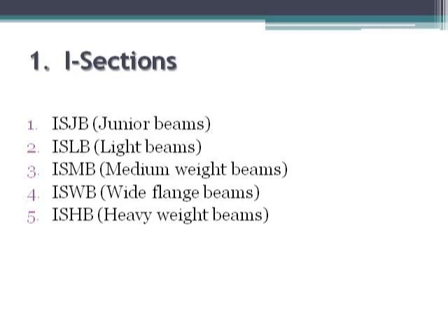Loads which are coincident with the major principal axis are called lateral loads. So for supporting lateral loads, we require more moment of inertia or section modulus about the YY axis, which is the minor principal axis. As I said, for the same height, ISWB section will provide more moment of inertia about its minor principal axis as compared with its counterparts. Hence, ISWB section will have more lateral bending strength, as it gives more moment of inertia about the minor principal axis that is required to support lateral loads.